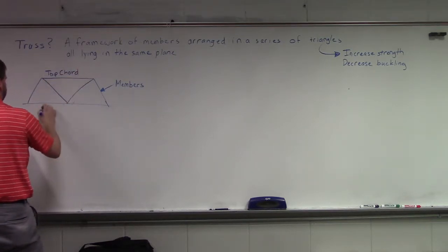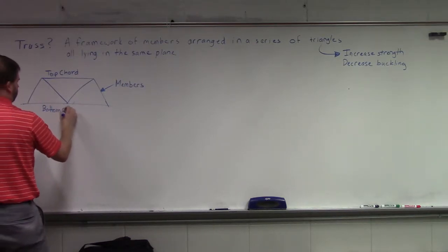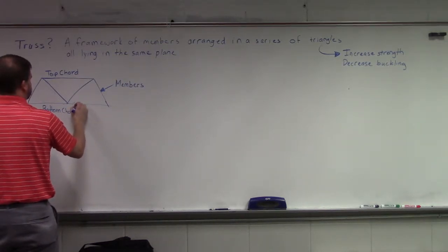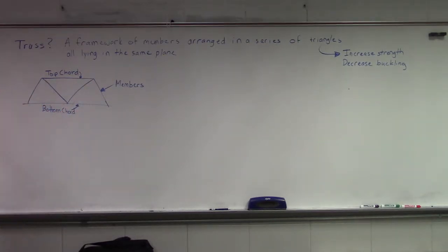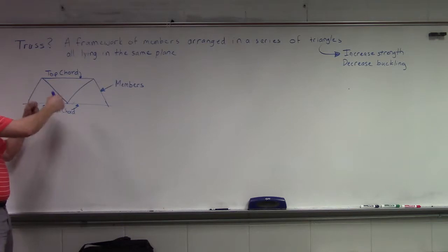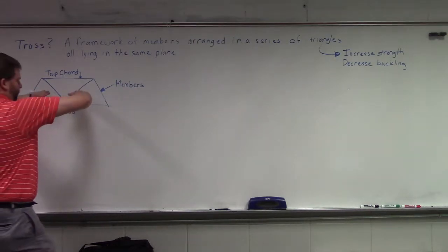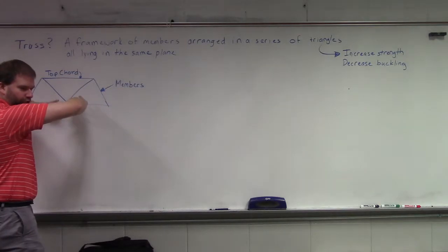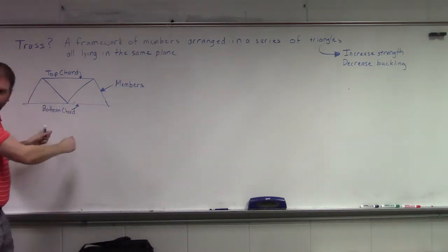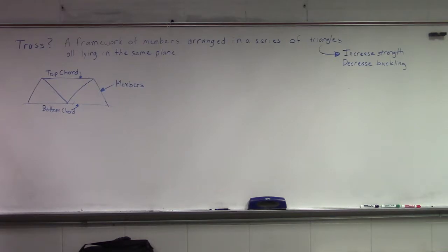We have our top chord, and we have our bottom chord. When we think about, as we're deforming our truss, whether it be from the effects of gravity, or the material itself, various loading pressures that we can put on them, typically speaking, what is happening to our bottom chords? Are we putting them into compression or into tension? Tension. As the truss deflects, these members are going to be pulled down. That bottom face is going to experience tensile forces.